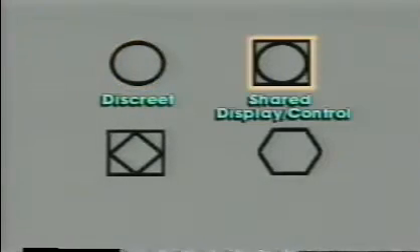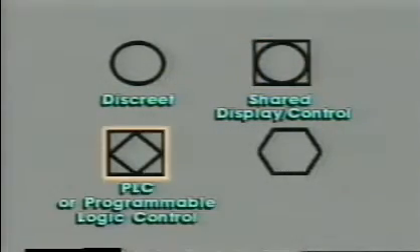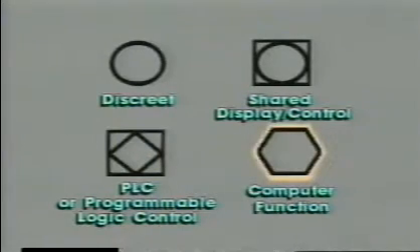You may already be familiar with many of the symbols used in instrumentation diagrams. Understanding these symbols helps to interpret these diagrams for troubleshooting or diagnostics. A plain circle or balloon indicates a discrete instrument. A circle in a square represents shared display or shared control functions. A diamond in a square represents a programmable logic control or PLC. A hexagon indicates a computer function.